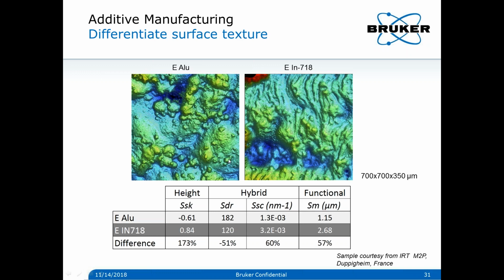Now we see that we have partially non-melted particles. We form blobs, so maybe not the perfect process. And here we nicely see for Inconel a melt front being moved around, with only a small amount of unmelted or large particles.